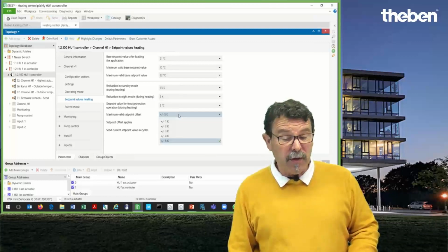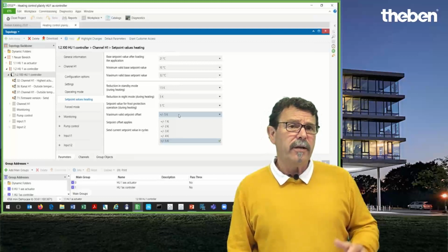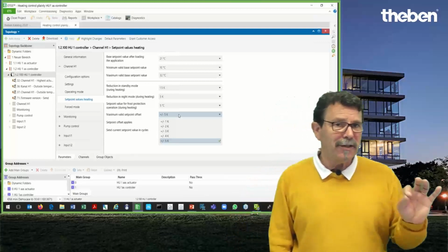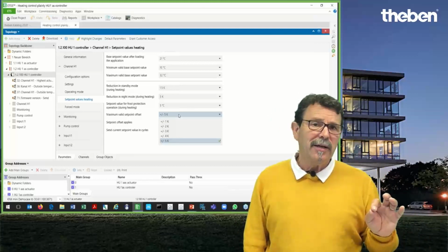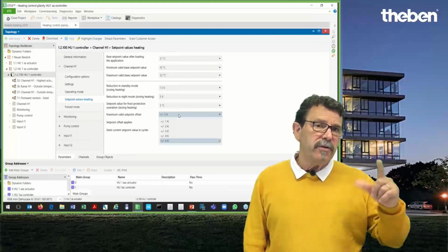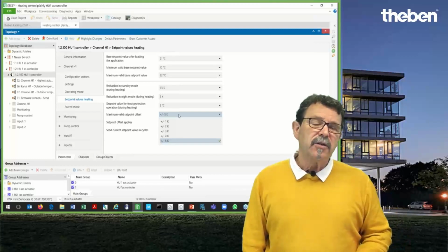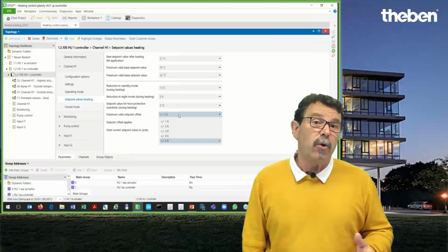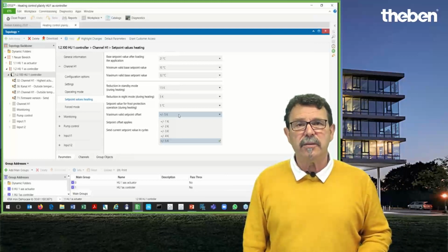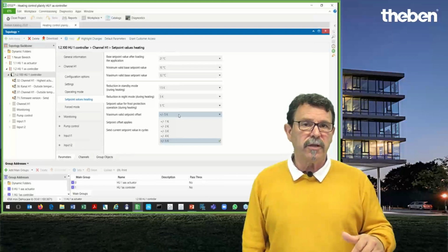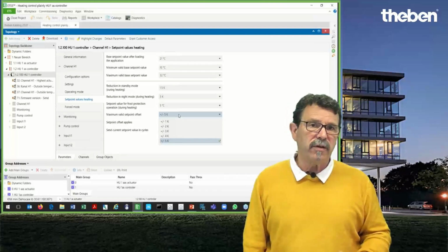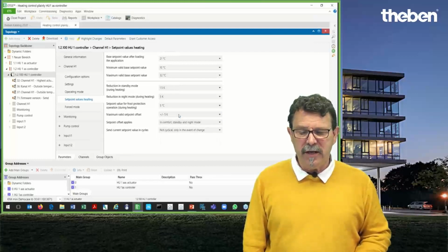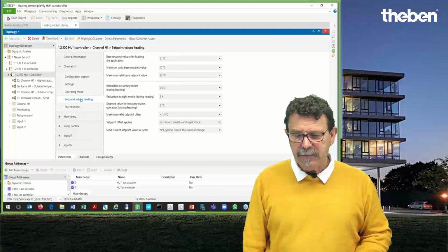This one could be of interest when you intend to integrate this kind of small, smart and fancy heating control into a visualization. Here you can adjust the limit. How wide can the set temperature be modified? Just 1K up, 1K down, or up to 5Ks up, 5Ks down. That's up to you. This you can limit in these application settings.